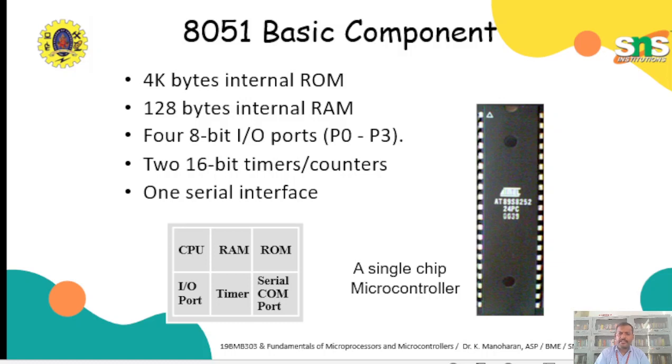So this is an event. Each time a person enters, it will be counted as a clock pulse and the counter will be incremented. The same 16-bit timer can act as a counter, so we can configure it as an internal timer or a counter. If it counts internal pulses, it is called a timer. If it counts external pulses, it is called a counter. It consists of 2 timers or counters, that means timer 0 and timer 1. Both can be used as a timer or counter, or one can be used as a timer and one as a counter. Again, it supports 4 modes of operation that we will see later.